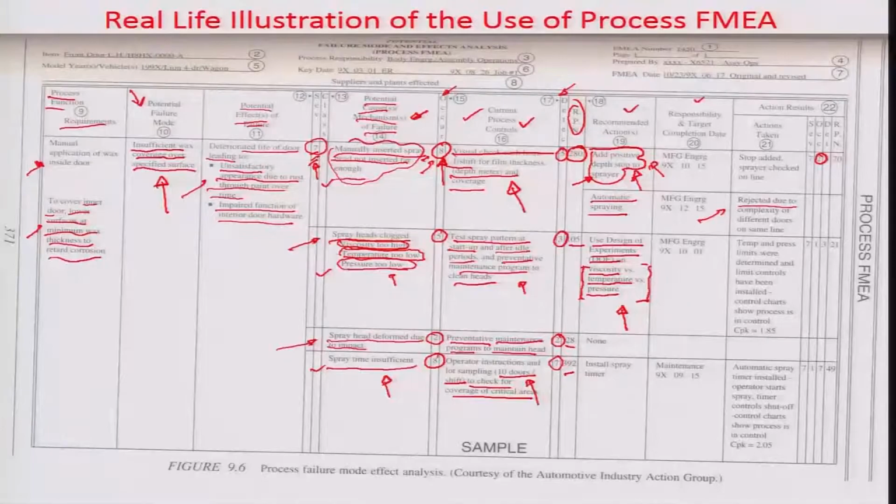Also, an additional checkpoint is recommended, where the QA recommends that a fraction defective chart be plotted here in order to show how many problems of insufficient wax coverage result due to this particular reason. Whether the temperature and pressure limits are obeyed or not gives you an idea of what is going to be the fraction defective coming out of the particular line.